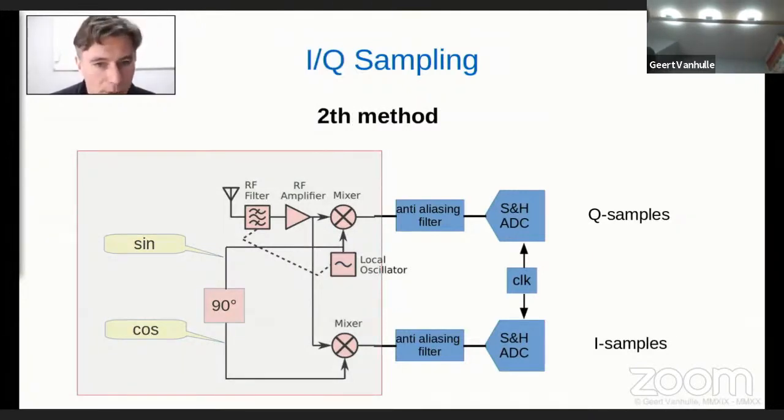replace this analog part, because as you see, we still have what we have discussed in the first part, this analog stage where we have this mixer and analog oscillator. We have to have some compensation if there are nonlinearities. We have to take care of propagation delay, all these kind of things. Our 90 degrees shift needs to be accurate. If we have a 1 degree error there, it means that our resulting samples will be incorrect in phase and not actually the correct samples to work with. So all processing done digitally later will have this error margin.